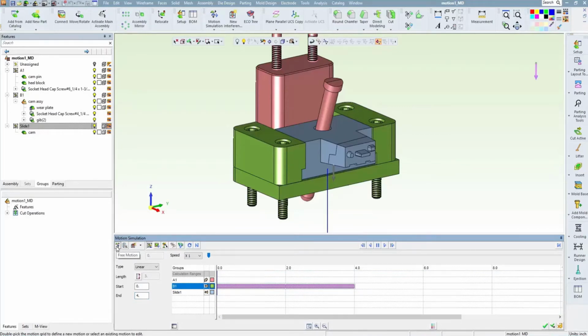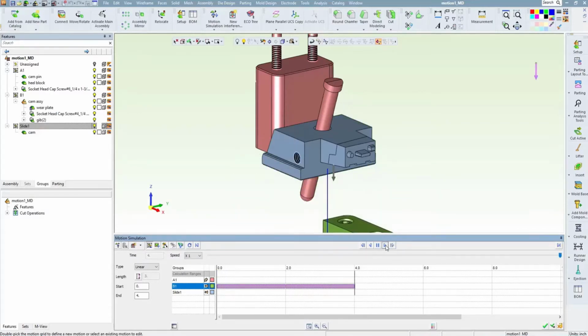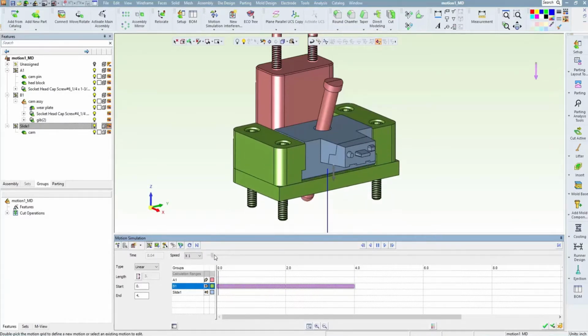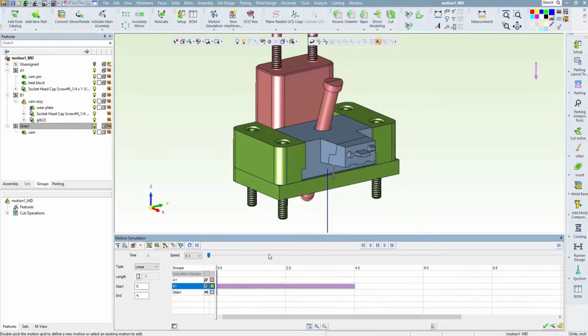Rule 5 suggests that you test the input force by running the motion in free mode. Free mode is a toggle to run motion without any calculation. So it's just a visual mode to make sure that the force you define is correct before you wait on the actual calculation.